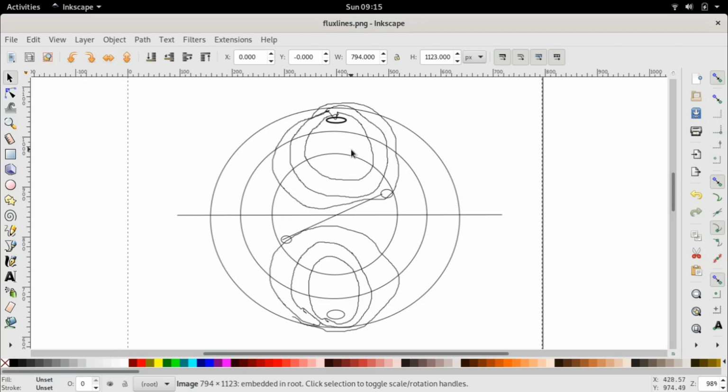So now the question arises: can we conclude this for any induction motor? And the answer to that is no. It depends on the construction of the rotor. In this particular case, since the rotor is cylindrical, if we assume the circumference to be smooth, then the reluctance of the flux produced by the stator current will not change, and therefore the stator inductance is constant. Now in this lecture, I'm going to show you another type of induction motor, which is a salient pole induction motor, where the rotor consists not of a cylinder, but of salient poles.